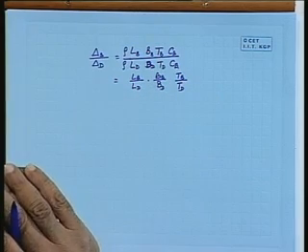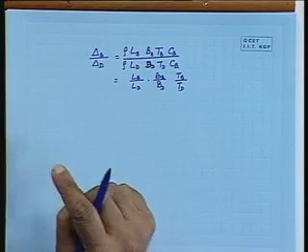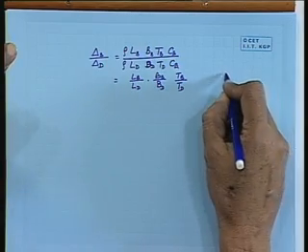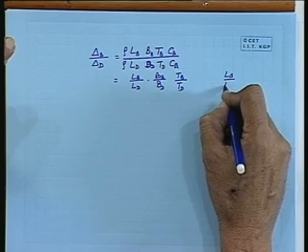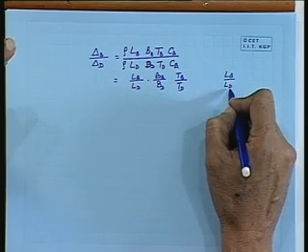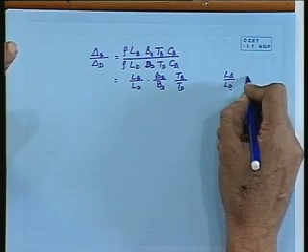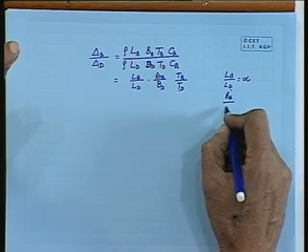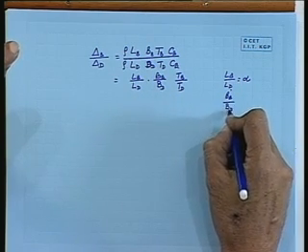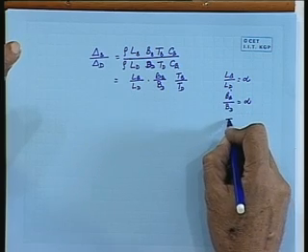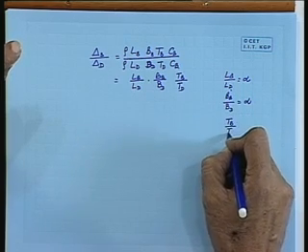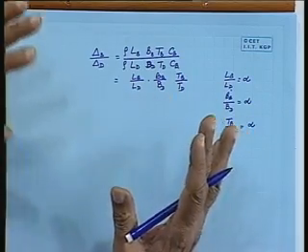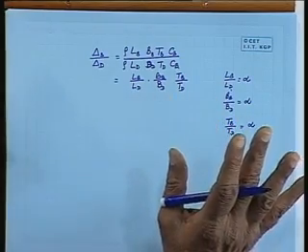and if I assume that the linear proportions of the two ships are identical, and if we say that LB by LD, that is basic ship to design ship, is alpha, B of the basic ship by B of the design ship is also alpha, and the corresponding draft is also alpha. That means it is just a scaled up or scaled down ship. Okay.